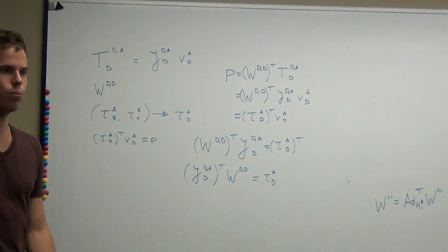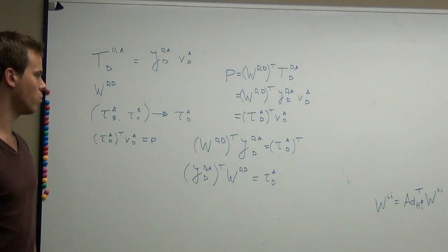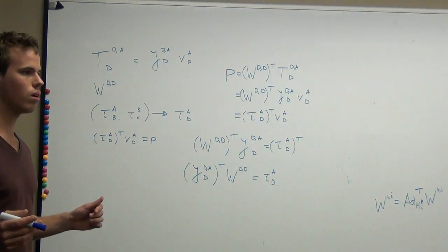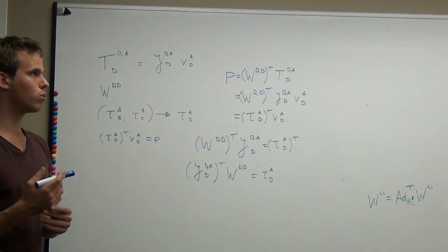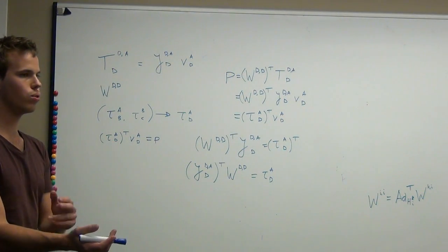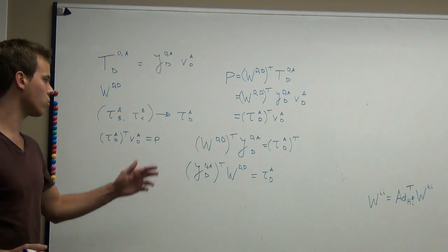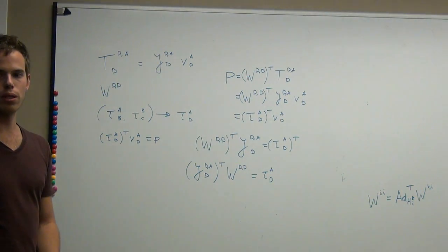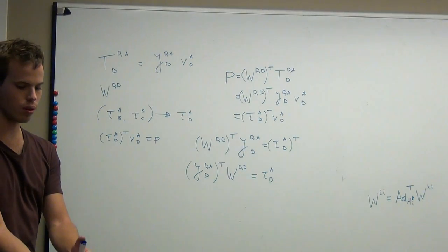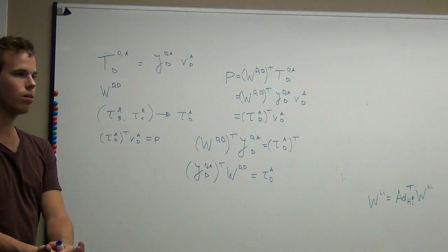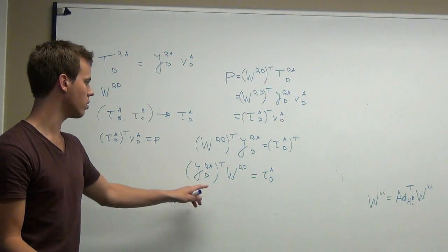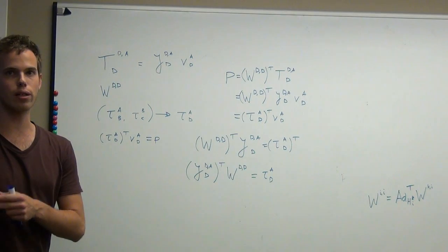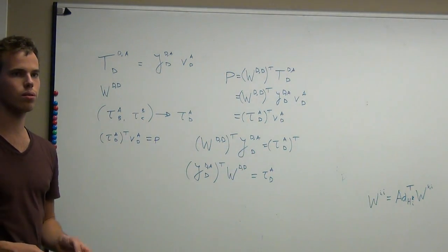It's a very well-known standard equation in robotics. That's where it comes from. So just power equivalence, whether you talk about twists and wrenches or joint velocities and torques, results in this equation. So basically, if you want to exert a certain wrench with your end effector, then this equation gives you the torques that you need to exert in all of your actuators to achieve that wrench.